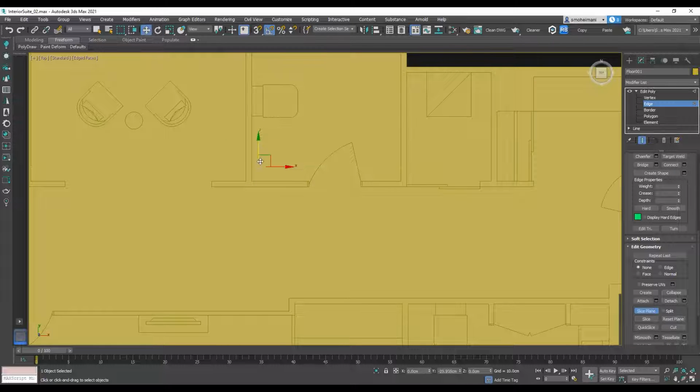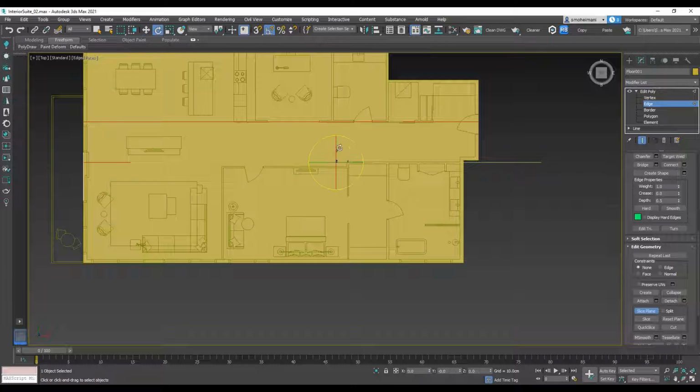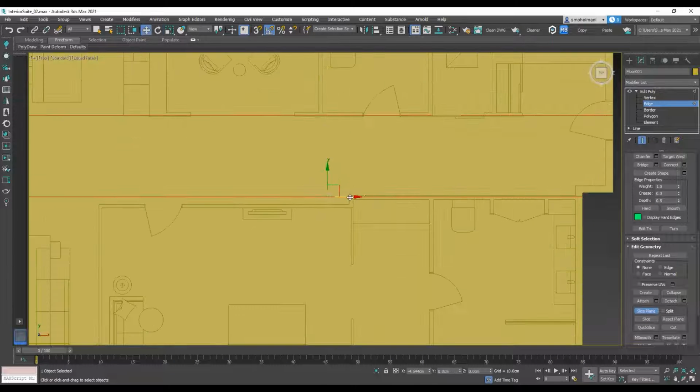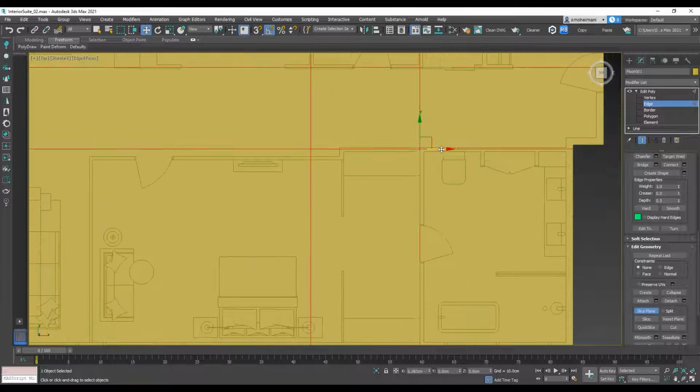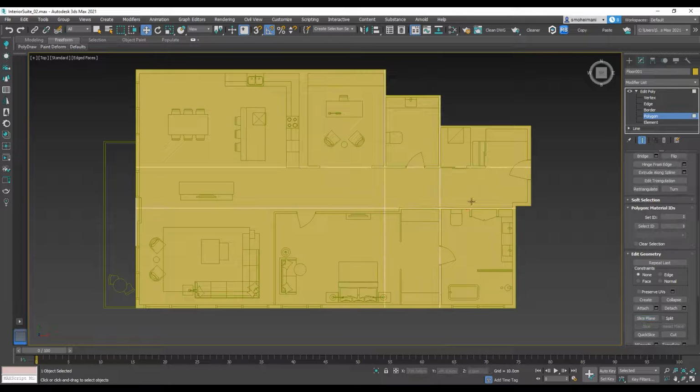So rotate it here and put it in the corner of the wall and hit slice to make the edge, and another one here for the ensuite and hit slice again, and then rotate the slice plane to make the other walls. After done with that, it's time to go to the polygons, select polygons for the floor of the powder room and ensuite and detach it.